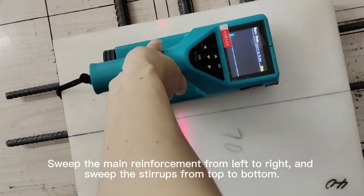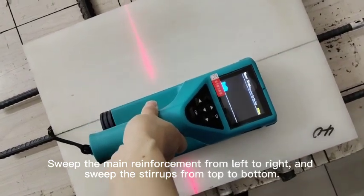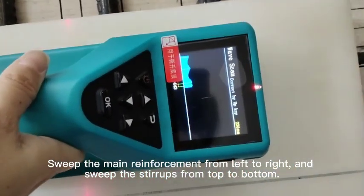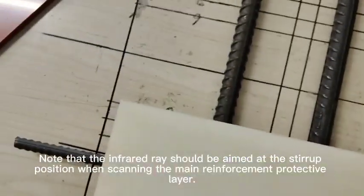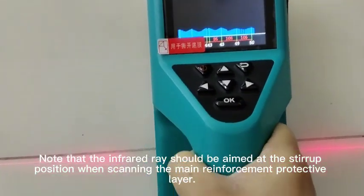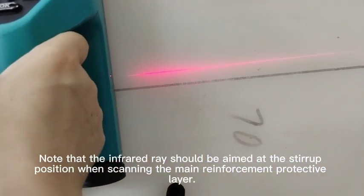Sweep the main reinforcement from left to right, and sweep the stirrups from top to bottom. Note that the infrared ray should be aimed at the stirrup position when scanning the main reinforcement protective layer.